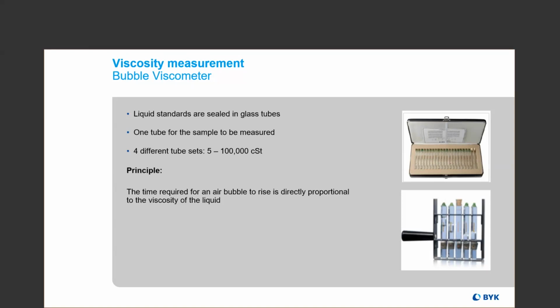And the measurement principle is that the time required for an air bubble in the liquid to rise is directly proportional to the viscosity of the liquid. And so the faster the bubble rises, the lower the viscosity.